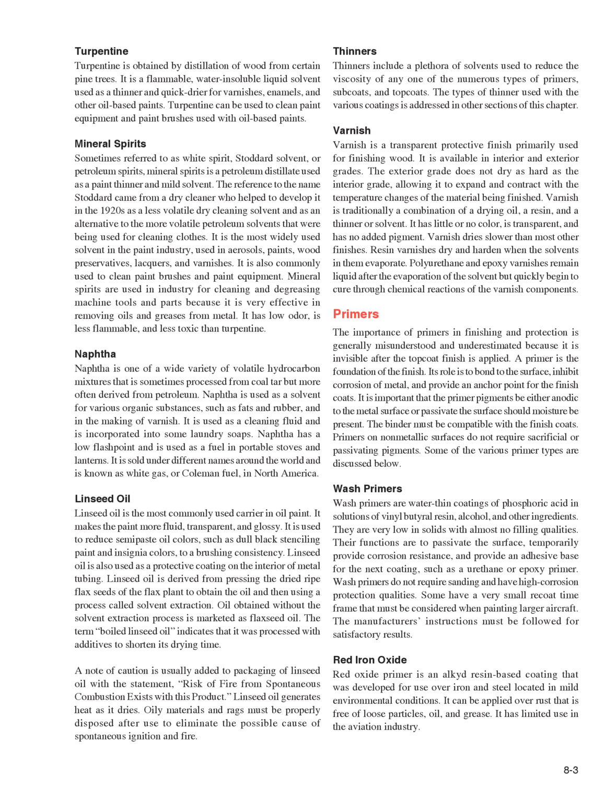Primers. The importance of primers in finishing and protection is generally misunderstood and underestimated because it is invisible after the topcoat finish is applied. A primer is the foundation of the finish. Its role is to bond to the surface, inhibit corrosion of metal, and provide an anchor point for the finish coats. It is important that the primer pigments be either anodic to the metal surface or passivate the surface should moisture be present. The binder must be compatible with the finish coats. Primers on nonmetallic surfaces do not require sacrificial or passivating pigments.